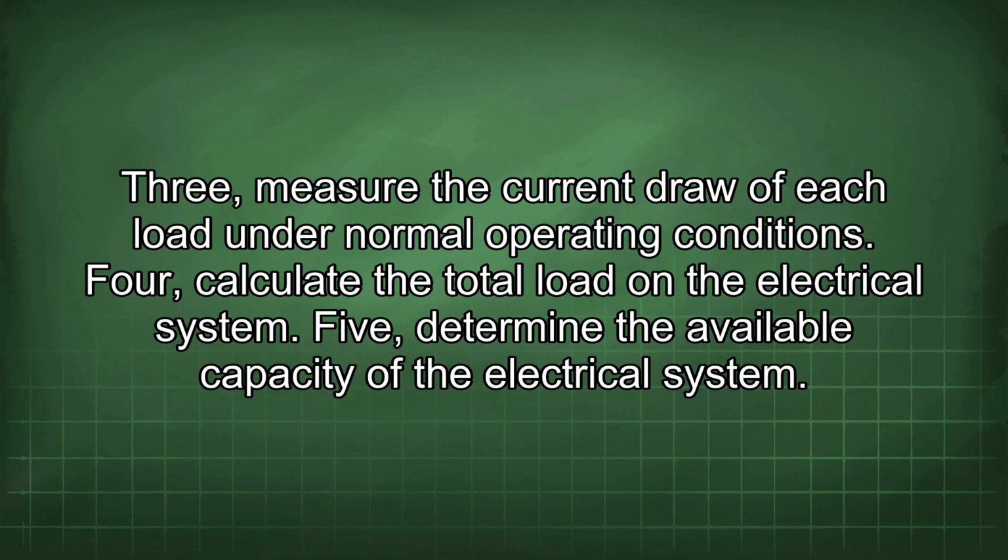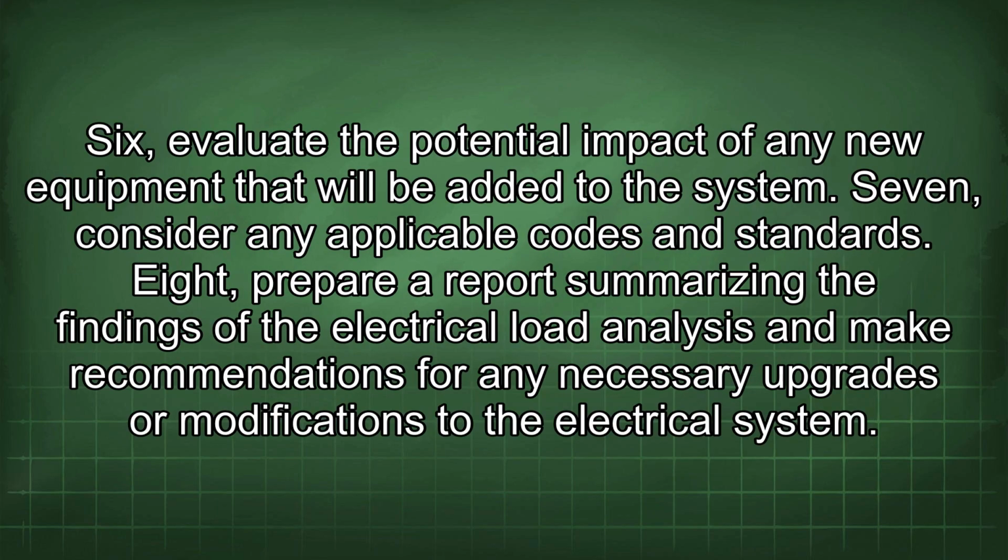4. Calculate the total load on the electrical system. 5. Determine the available capacity of the electrical system. 6. Evaluate the potential impact of any new equipment that will be added to the system. 7. Consider any applicable codes and standards. 8. Prepare a report summarizing the findings of the electrical load analysis and make recommendations for any necessary upgrades or modifications to the electrical system.